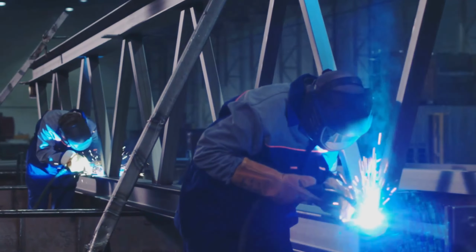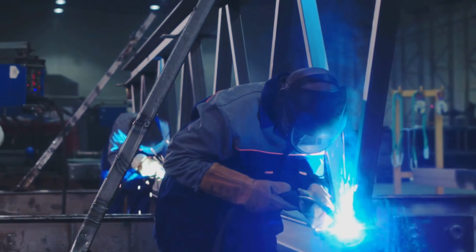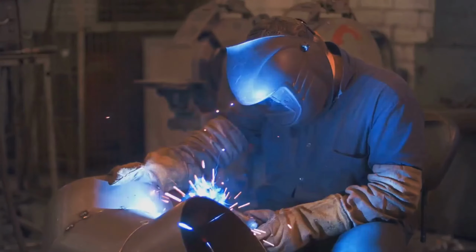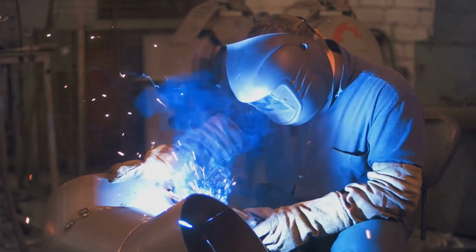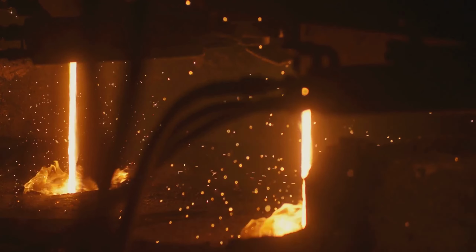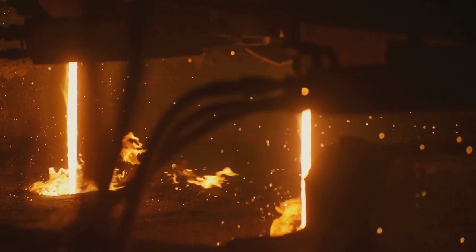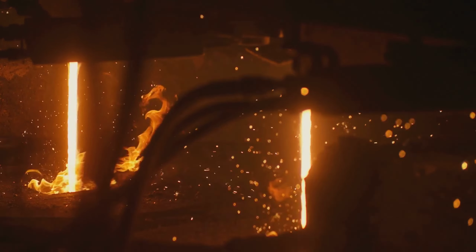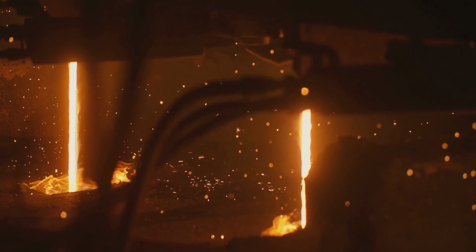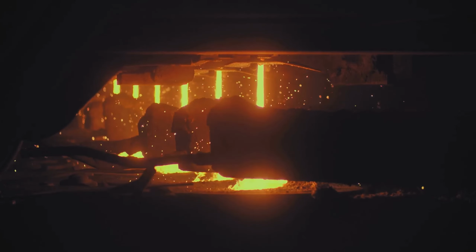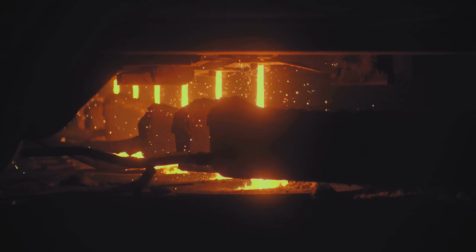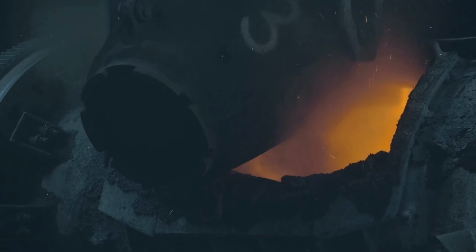The application of MHD in metal casting provides a non-contact method to manipulate the molten metal, which is especially beneficial in handling high temperature and reactive metals. MHD can mitigate turbulence, reduce defects and inclusions, and promote directional solidification.